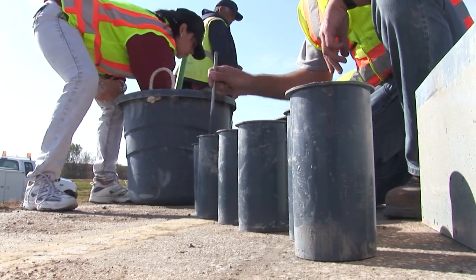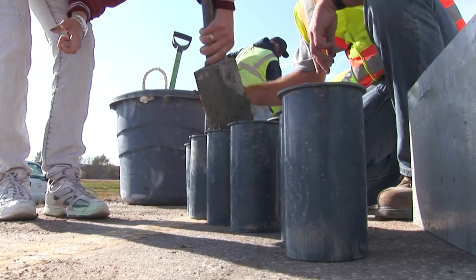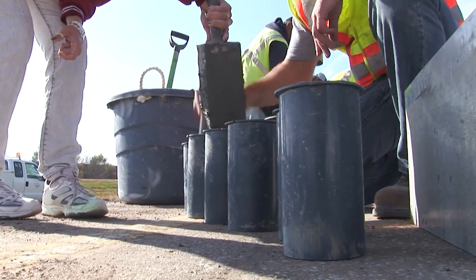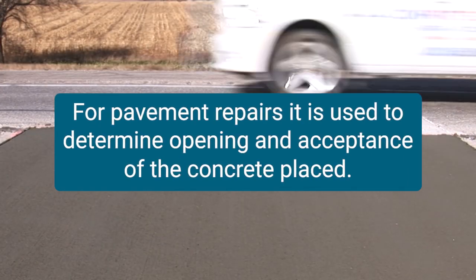The Nebraska Department of Transportation uses the maturity method as an option to test cylinders for concrete pavement repairs. For pavement repairs, it is used to determine opening and acceptance of the concrete placed.